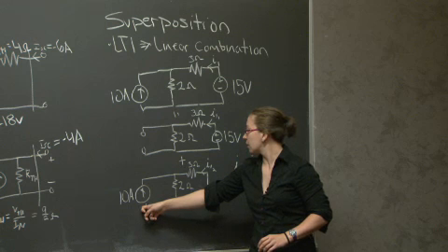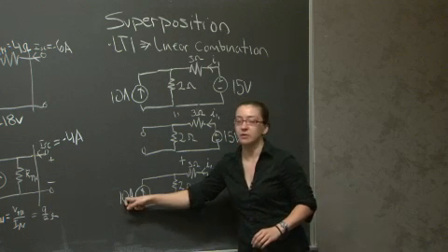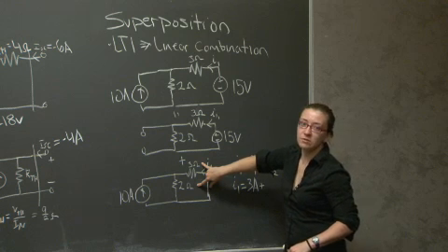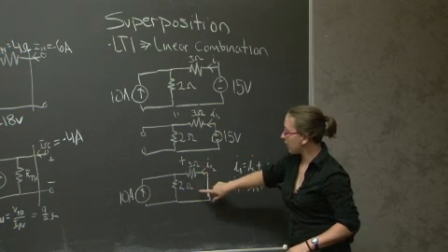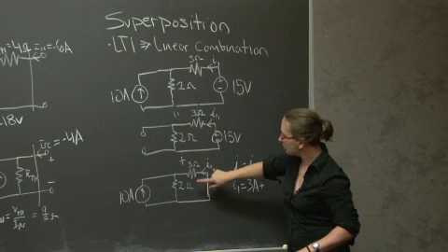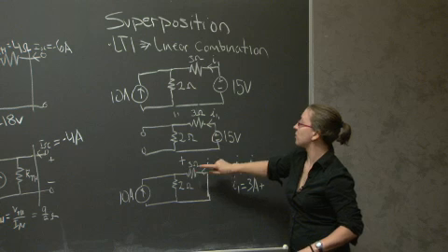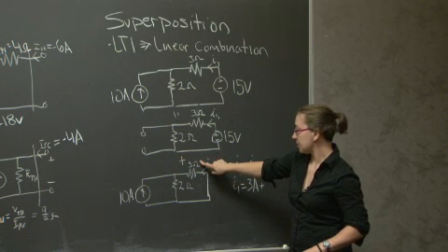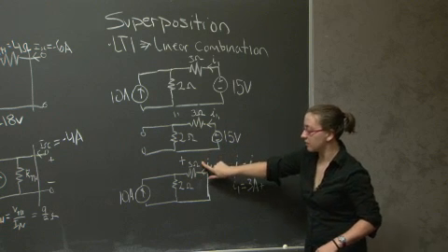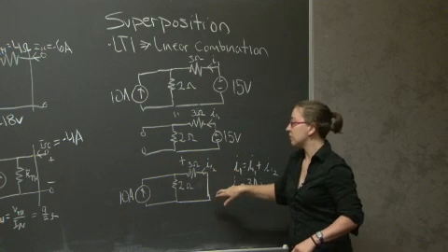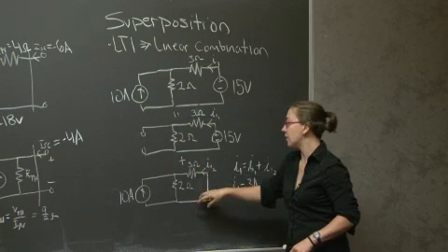In this circuit, I'm actually going to have to use a current divider. Identify that I have 5 parts total to distribute among these 2 branches. Identify that this side is going to get the inverse of this side's contribution to the total parts. Or this side is going to get the proportion of parts equivalent to this side's contribution. And vice versa. That this side is the side that I'm interested in. And so 2/5 of the total current flowing through this current divider is going to end up in this branch.